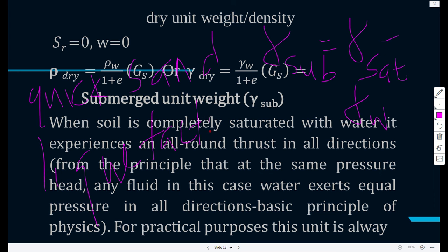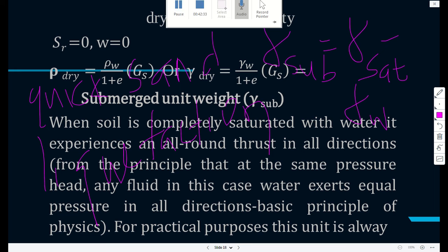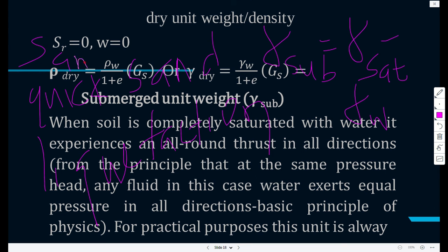Quicksand condition is when it rains and you have loose soil, not soil, loose sand. Sometimes immediately after it rains, you can see water gushing out of the soil, carrying sand with it in a manner, so it looks like the sand is boiling. That's why we call it. Actually, another name for it is sand boiling. Those who come from sandy areas, it is quite common, especially when you have loose sand. And this is a problem with construction on loose sand. Now, liquefaction is when this happens on large scale due to earthquake.